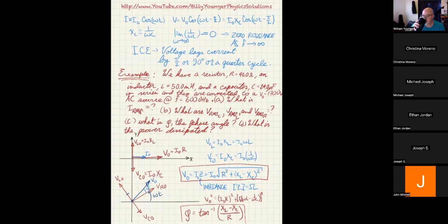Yeah, would it be possible to do IRMS squared times the impedance for power? No, I don't recall that working that way. I'm trying to remember any other versions of it. Oh yeah. So you can do I squared Z cosine theta, but not I squared Z.